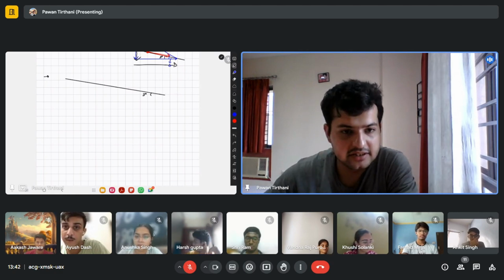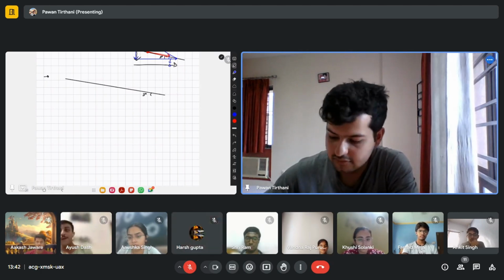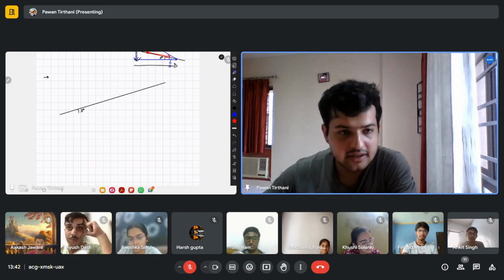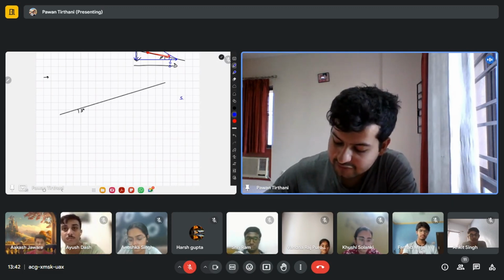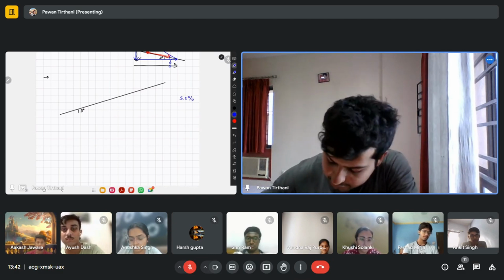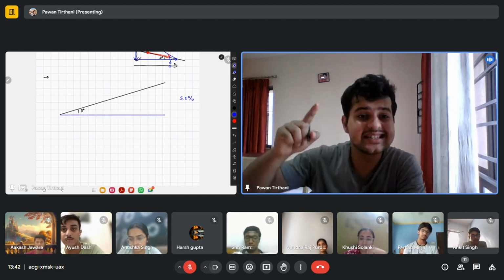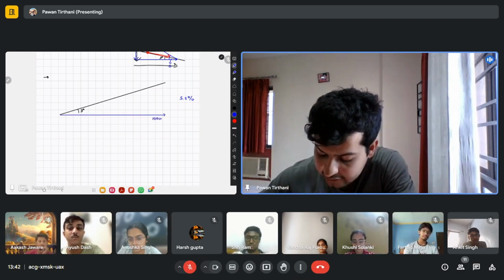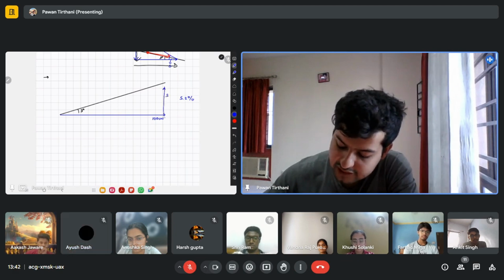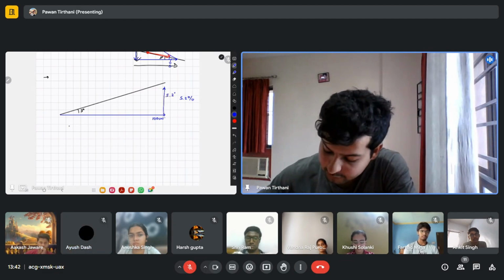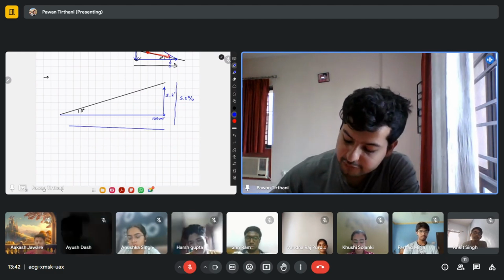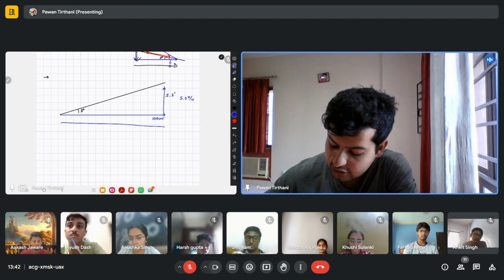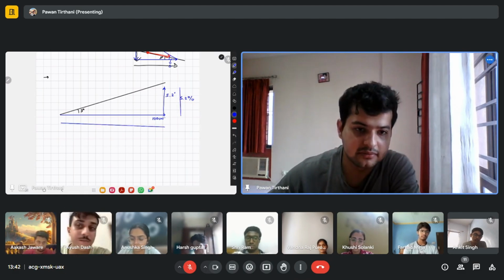तो ये 3 degrees को I can also express as a percentage. Let's say I am climbing in this angle. So this is my climb angle 3 degrees. This can also be told that okay, I am climbing at 5.2%. मतलब क्या? For every 100 units I go ahead, I go 5.2 units up. If I'm going 100 feet ahead, I'm going 5.2 feet up. If I'm going 100 meters ahead, I'm going 5.2 meters up. If I'm going 100 nautical miles ahead, I'm going 5.2 nautical miles up.